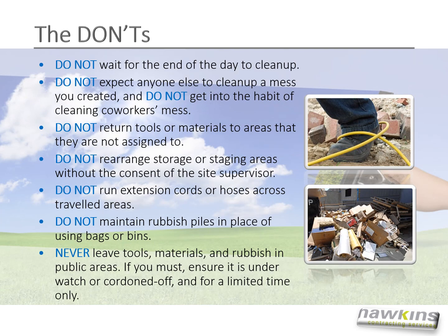The don'ts of housekeeping are as follows. Do not wait for the end of the day to clean up. Do not expect anyone else to clean up a mess you created, and do not get into the habit of cleaning coworkers' mess. Do not return tools or materials to areas that they are not assigned to. Do not rearrange storage or staging areas without the consent of the site supervisor.